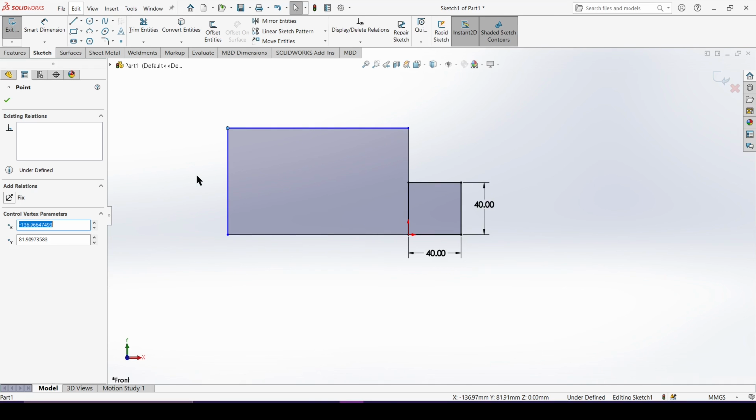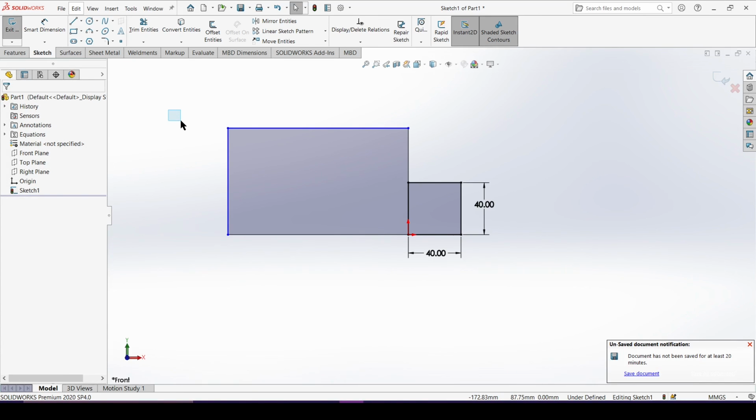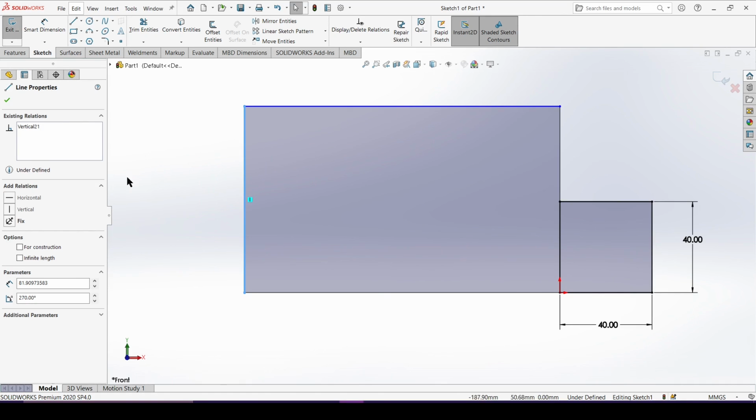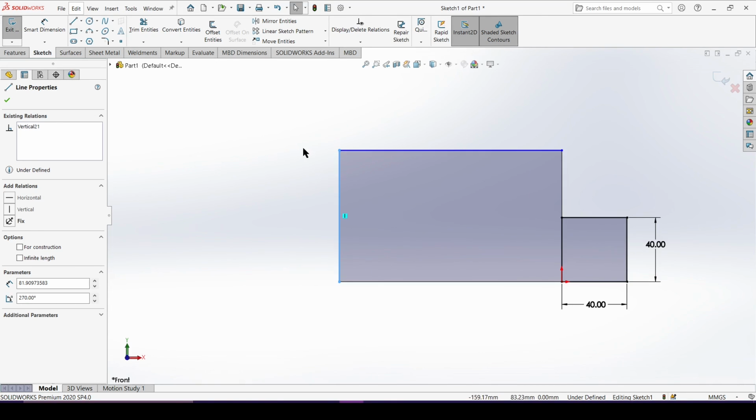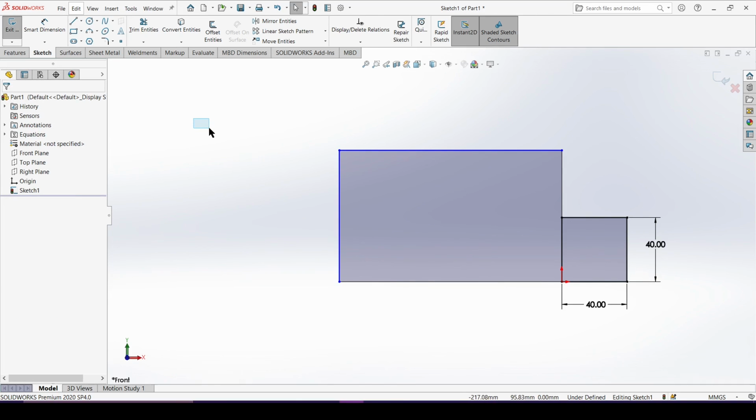Okay, how to select things. Now this is also a good thing. Of course, if you press the left click and bring it to the right side, it will create a blue selecting area, and that blue selecting area will select only those items which are completely inside it. For example, in my selection, only this line was completely inside this blue selection area, whereas these lines were partially inside. So only those things which are completely inside that blue selected area will be selected, right? How? When we are pressing the left key and pulling it to the right side.